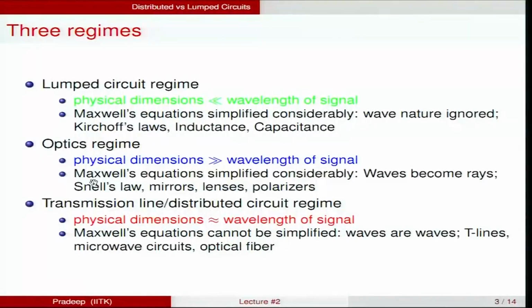The voltage at any point on a circuit depends on that particular point in the circuit. However, within a given wire itself, the voltage will not change from one point to another. Of course, on a transistor circuit, the voltage at the base is different, the emitter is different, and the collector is different. But at the base, 0.1 centimeter away or 1 centimeter away, if no circuit elements are connected in that region, the voltage will be the same. So what we mean is that even on a wire, in the lumped circuit regime, the voltage at all points is the same.